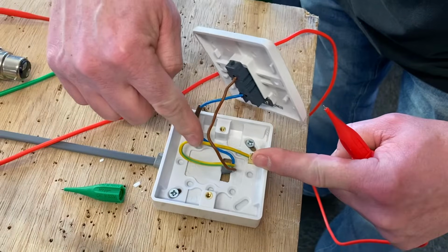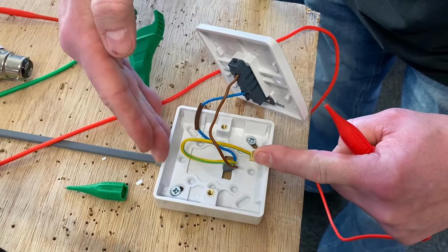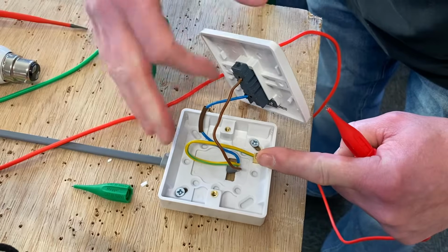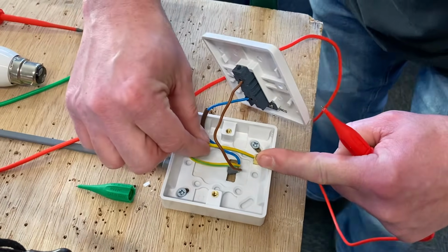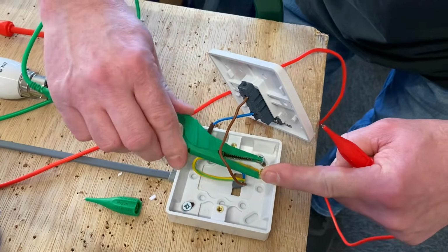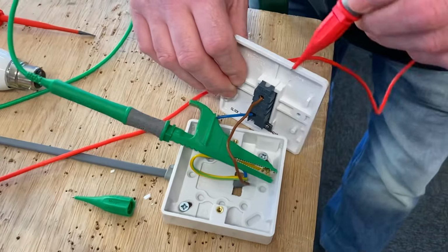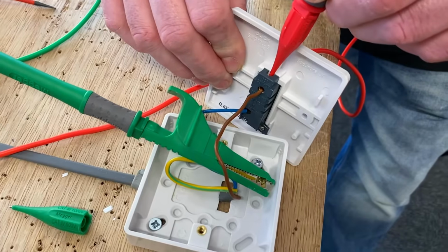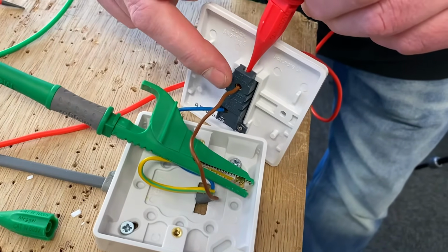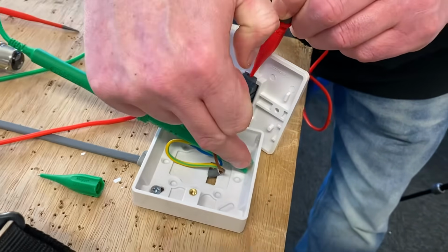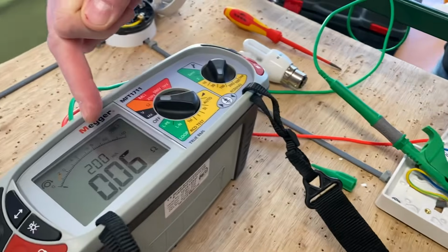But we need to prove it gets down here, because there's nothing suggesting that the minute we've left our installation that these switches are changed. So we need to prove the CPC gets to here. So if we clip onto the connection there in the back of the box, and we come into, and I'm going to go into the top where the common is. It wouldn't matter which one I go in because I've left it on, but I'm into the top position, I'm onto the CPC, and I go back and look at my reading.